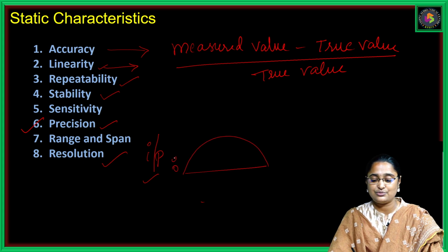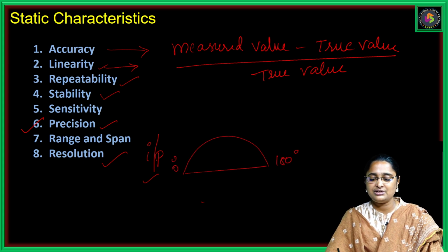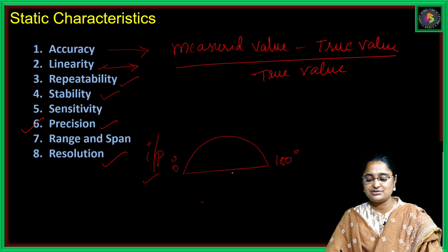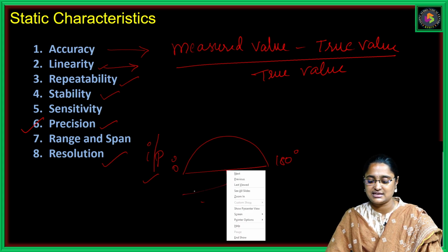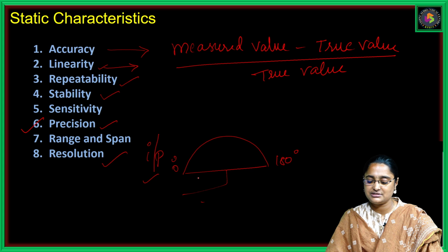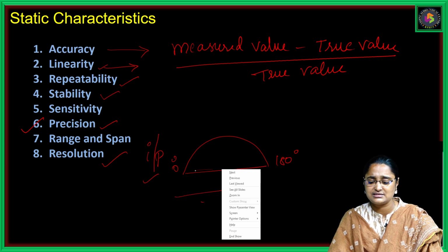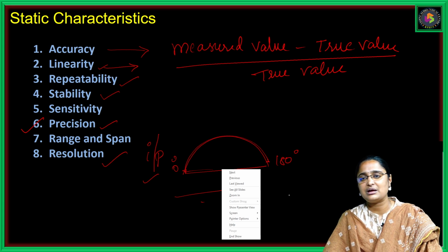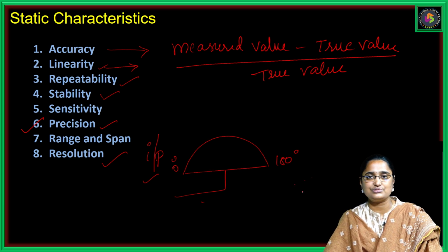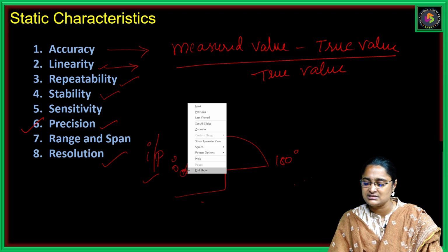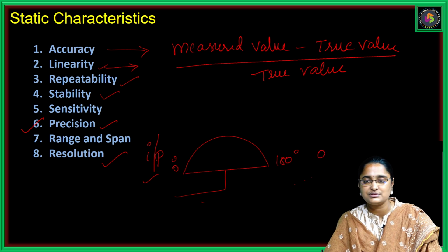If you want to measure rotation using that capacitive transducer, you will have a semicircle scale with readings from 0 degrees to 180 degrees, and the capacitive transducer is connected to this scale. Now when you rotate it from 0 to 180 degrees, it will give you relevant values as expected outcomes, right? So if I give 0 degrees, the output should be around 0.